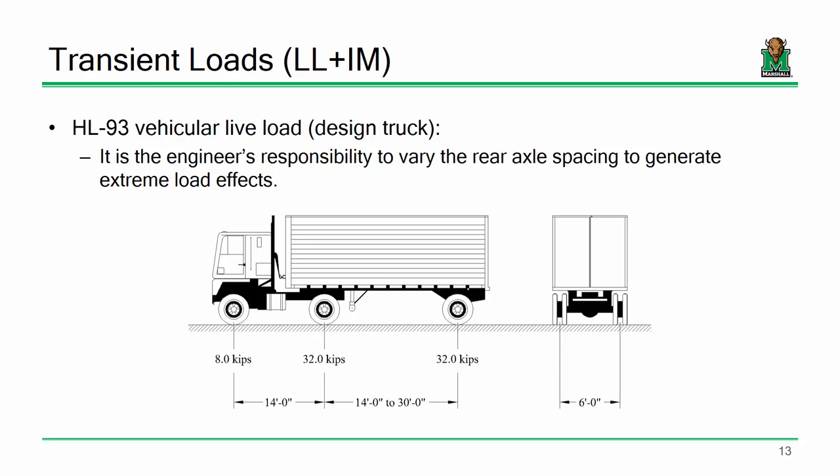I've got a pop quiz for you. Remember how I said HS20, the HS2044? If this axle weighs 8 kips, how much does each wheel weigh? What about here? What's 4 plus 16? That's where that comes from. No, this axle is 32 kips. Now, that's just off the image. We're saying 2 wheel lines. So I see what you're saying.